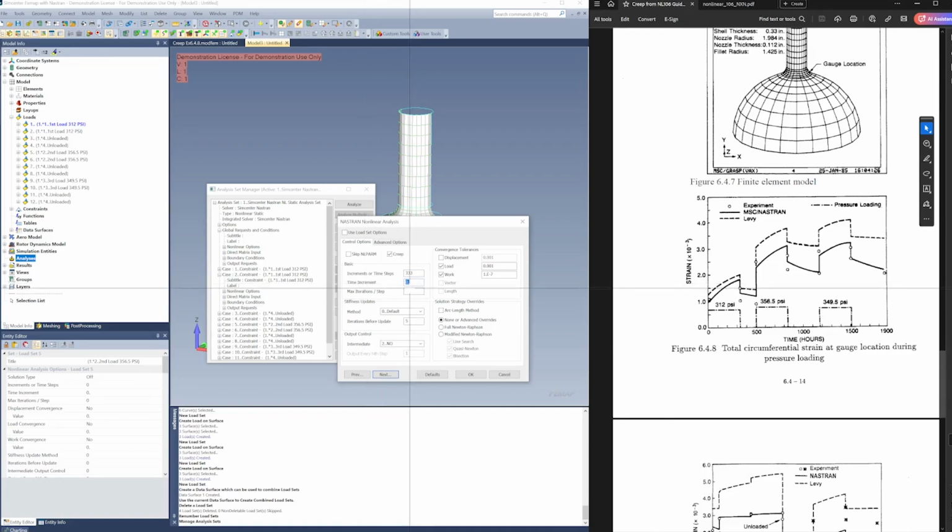Remember, that is based off of our material properties, our creep material properties. They were in KSI in hours. So for simplicity's sake, I'm just going to use one increment, so an hour increment. So it should give me 333 output sets just for this particular section of the creep analysis. And overall, we're going to end up with something like 1900 because I'm not going to quite do the math on some of these increments, or these time frames.